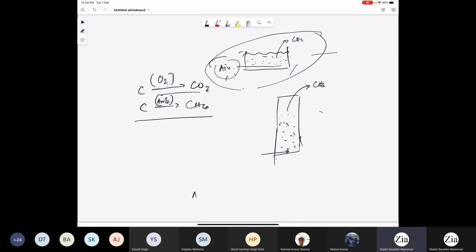So that's why wastewater having low carbon content is preferred for an aerobic reactor, because the aerobic reactor is more stable, very easy to build, and very easy to operate. A lot of other advantages are there. The only drawback is the cost due to aeration. So if you have very low carbon content and aeration is not that expensive, then you can choose the aerobic reactor system to treat low carbon content wastewater.